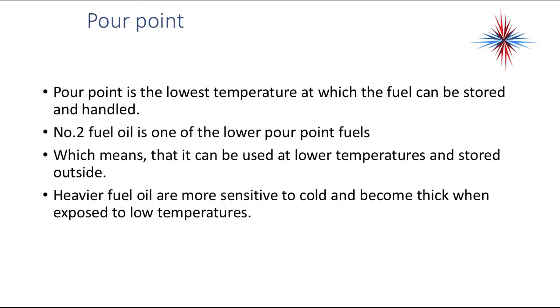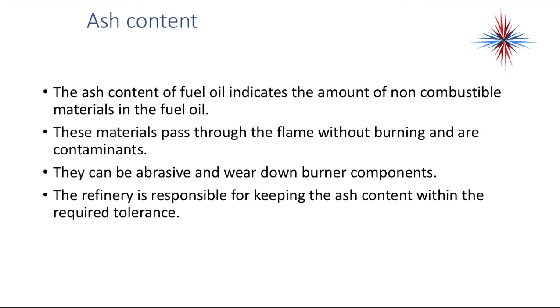Pour point. Pour point is the lowest temperature at which fuel can be stored and handled. Number 2 fuel oil is one of the lower pour point fuels, which means that it can be used at lower temperatures and stored outside. Heavier fuel oils are more sensitive to cold and become thick when exposed to low temperatures. Now up in the northeast part of the country, they do start mixing some kerosene, which is a number 1 fuel oil, in with the number 2 to lower the pour point for cold winter days.